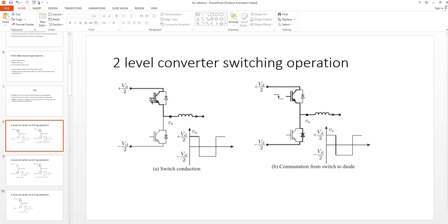They were used in industrial drives, home appliances, automotive drive systems, and in low voltage grid connected converters, etc. There are different advantages of using two level converters, like they have a smaller number of semiconductor devices, so the switching losses can be very low, right?